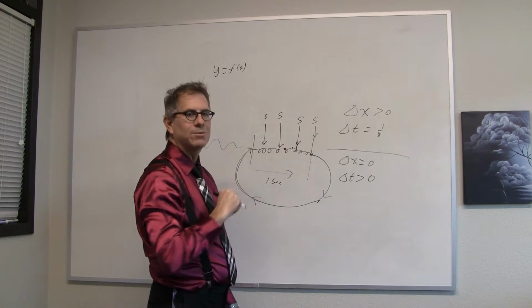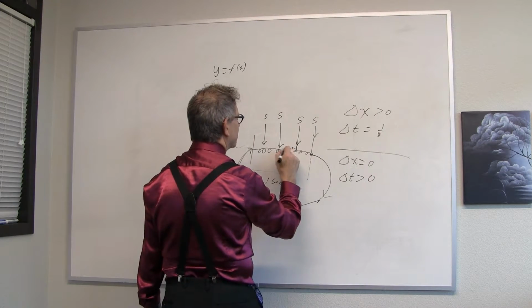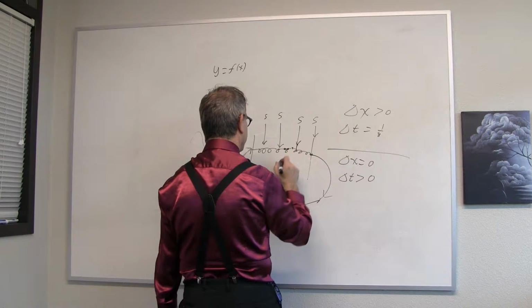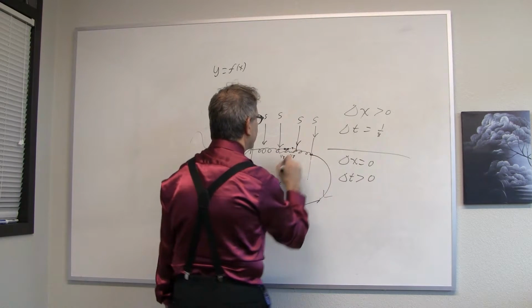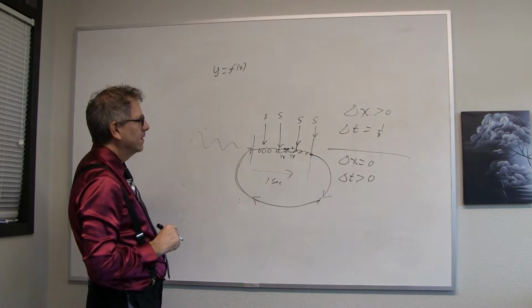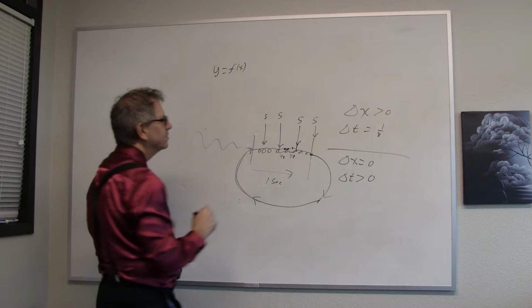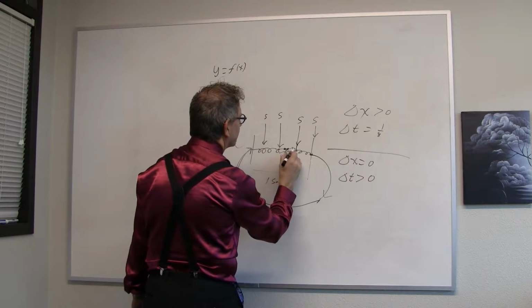If we want to be able to measure it within 1/8, worst case is a point that's exactly in between 2 sensors. So this is 1/4, this is 1/8. And within 1/8 of a second, we're guaranteed that the point that we're interested in is going to hit a sensor if it's within here.